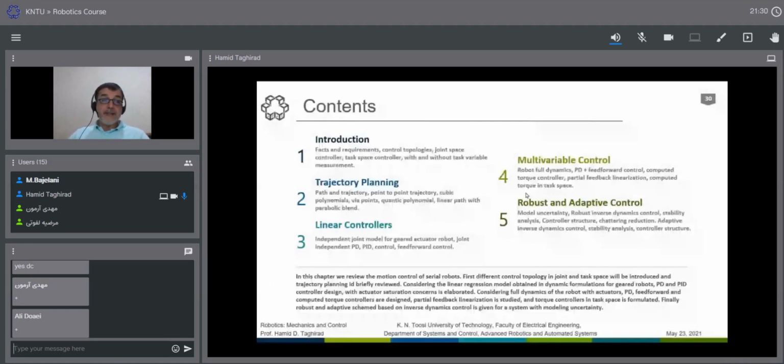It is also very practical and based on experiment, but we don't use just the nominal model for the system. In linear H-infinity control, we say, okay, this is the nominal one, and we also encapsulate the uncertainty. How accurate is this model? If you have these two pieces of information bounded, then you can have a very effective and celebrated method to use in the controller. So always you can have some robust controller to be added to the system.